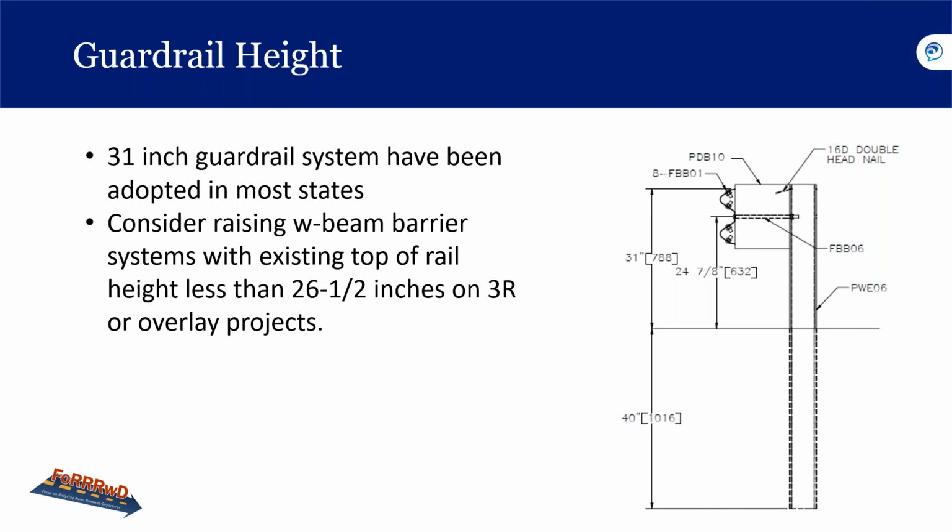It is not cost-effective or practical to raise all existing guardrail to the current criteria on a highway agency's entire roadway system. However, guardrails should be upgraded as part of a reconstruction or new highway construction project. So that is what the AASHTO Roadway Design Guide says in response to that question.